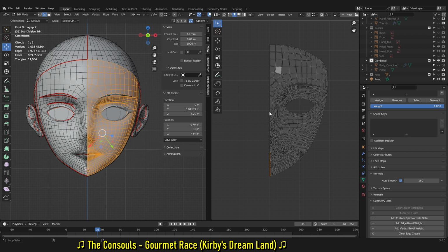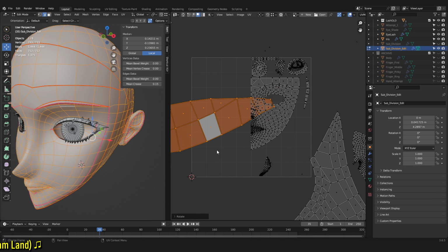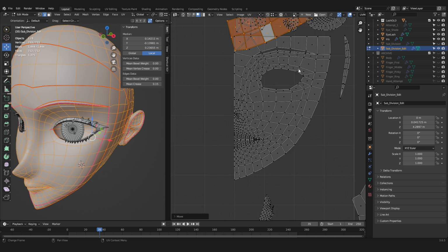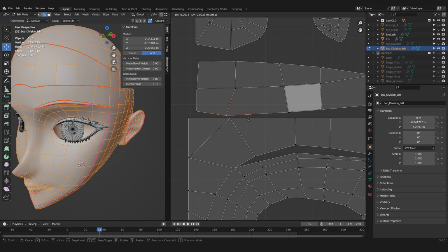Once in place, select the edge, make sure the edges are all aligned and press N and then set the X value to 0.5. At times you might want to expand a UV island without having to unwrap it again, causing you to start from scratch. One method is to unwrap the new area and connect it manually by using vertex snapping.